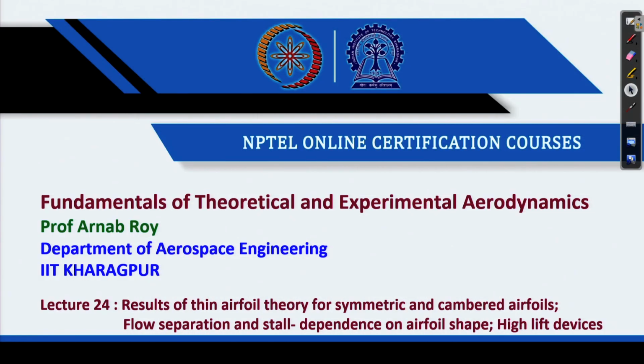In this lecture, we discuss the results of thin airfoil theory when applied to symmetric and cambered airfoils. Further, we discuss the dependence on airfoil shape, how it affects flow separation and stall when we consider real viscous flows, and we will introduce a discussion on high lift devices.